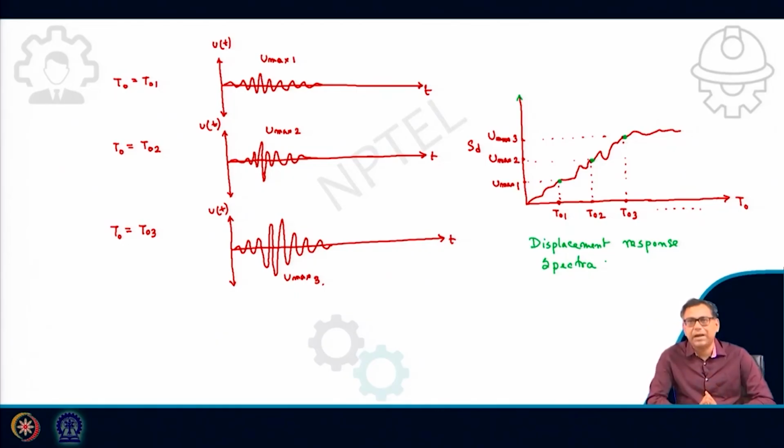For now, if you apply a real earthquake motion to structures with different time periods, and you get the response of those cases, then you will get the expression of your displacement, and then you plot them with time for different cases.